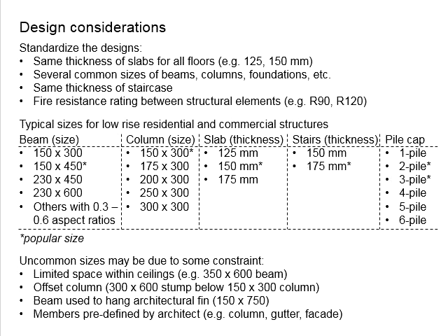Typically for low-rise residential buildings, 150 times 300 should be sufficient, and there are ways for you to distribute the load. If you find the capacity is insufficient, most likely the columns are quite far apart, and you can hide more columns in the wall. Some may want to increase the size to 150 times 350 or 150 times 400.